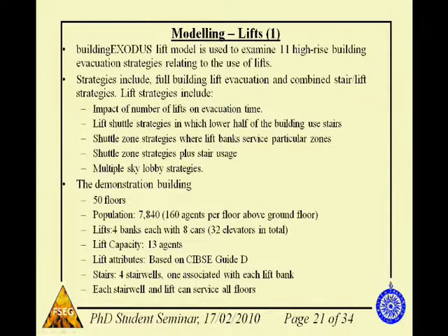With regards to modelling lifts, we examined a series of 11 high-rise building evacuation strategies, and these explored the impact of the number of lifts on the evacuation time, the lift shuttle strategies, zonal strategies, and sky lobby strategies. The demonstration building we used for these simulations was 50 floors high, with 7,840 agents. This is 160 agents per floor above ground.